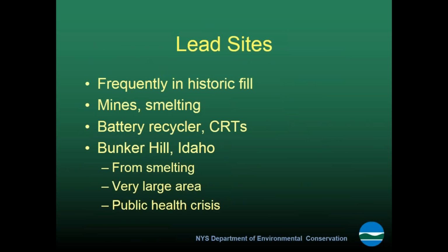The most frequent situation where you're going to come across lead is in historic fill. Back when we had leaded gasoline, there was air deposition of lead throughout the country and throughout the world. And there were other sources of lead that found their way into ash and landfills and so on, and that's where you get the lead in your historic fill. There are some mines in the Northeast. New York has a couple that we're currently remediating.